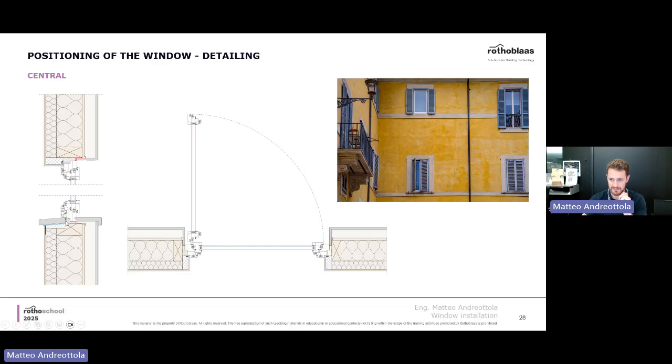You see that it's sealing that gap over there, but you're using, in this case, this protect band, or ground band or something similar. You're using it also to waterproof the window, the external window sill that you see right now. In this case, it's done of stone, but it could be anything on the outside.